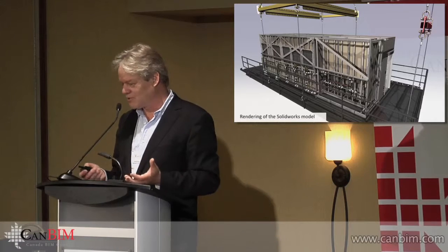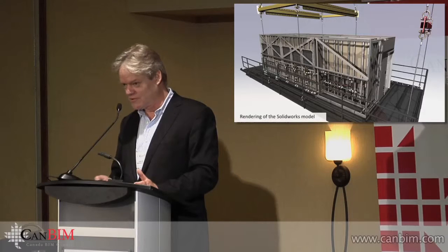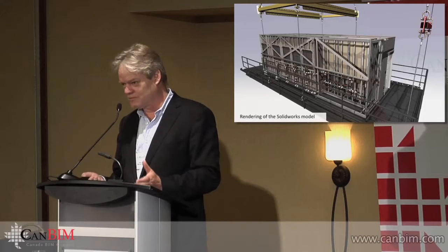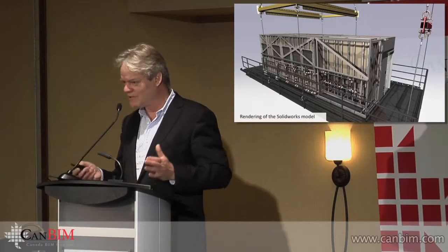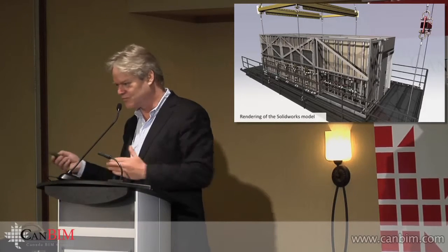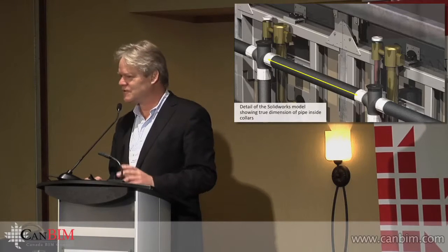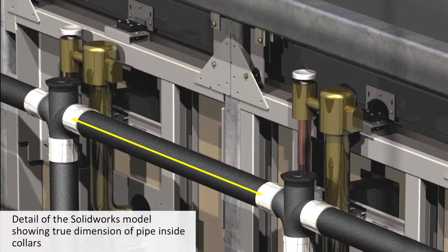Even the toilets, we didn't have a complete model for them, and they're made of ceramic, and they have all kinds of weird hollow voids in them. So what we did was we actually put them on a scale and then moved a dowel back and forth underneath them until we found their center of gravity, and then put them into the model with those properties as kind of a separate menu of properties associated with that object. You see here that those little triangular brackets, for instance, that go between the studs and that horizontal tube, that is the cut file for that component.